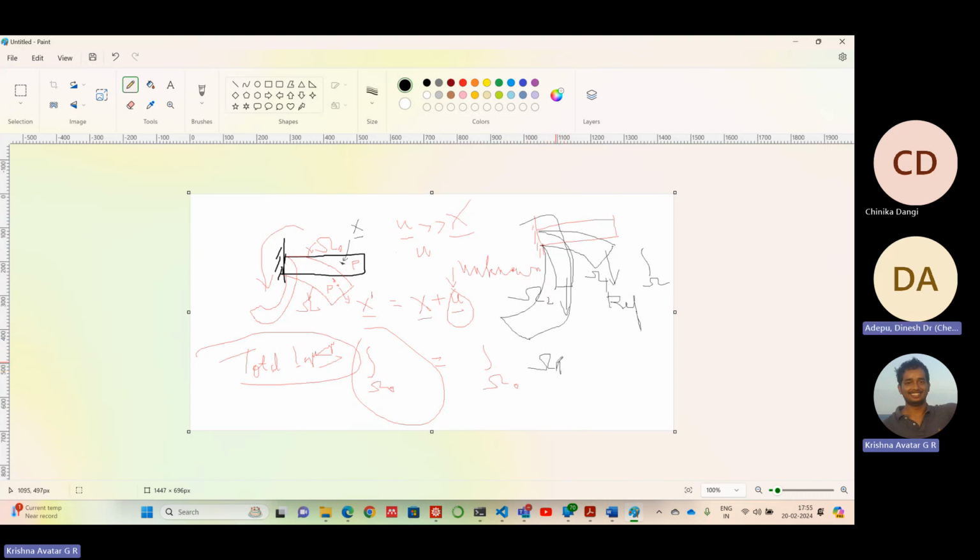So when we are determining omega n, our reference configuration will be omega n minus 1. So it's like we are incrementally approaching the final deformation using a series of initial configurations. That is what we call the updated Lagrangian formulation.